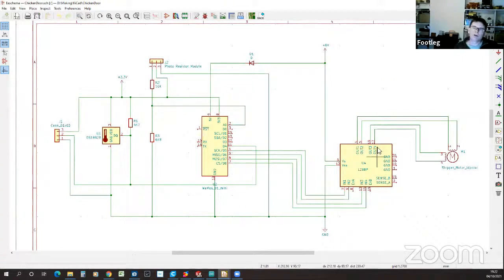And I discovered that you can run a stepper motor off a pair of motor driver outputs. So the 4 wires of the stepper motor are wired up to the motor driver, and that gives me control of the motor. For people who haven't used a stepper motor before, it's like a motor where you can programmatically turn it fractions of a turn. So you can say do 1/8 of a rotation anti-clockwise, or turn 20 times clockwise. So you can control it in code precisely, and that would be perfect for hauling the door up by winding up the string and unwinding it.